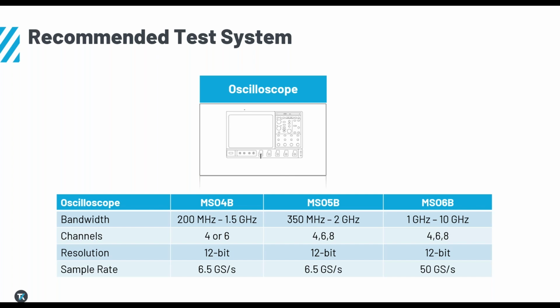Accuracy was another challenge. How do we get more accuracy within our measurements? And so within your measurement system, you have to look at not only the scope, but the probes. But to start, within your digitizing system, we have a 12-bit ADC. And so that's going to give you a lot better resolution within your measurements, DC, AC, et cetera.